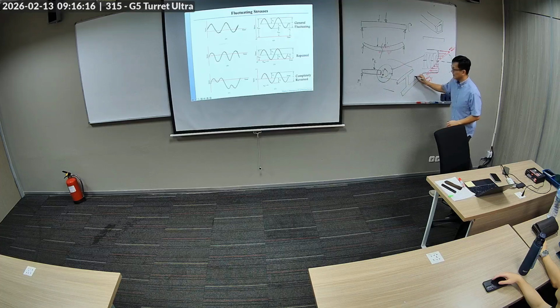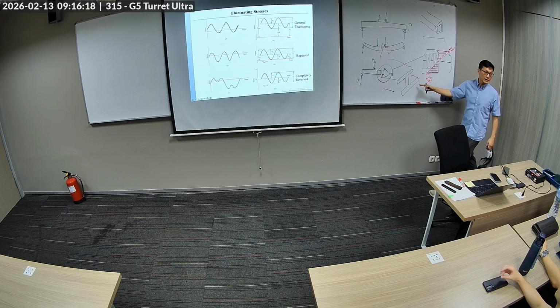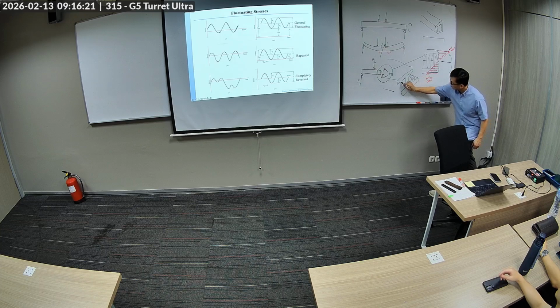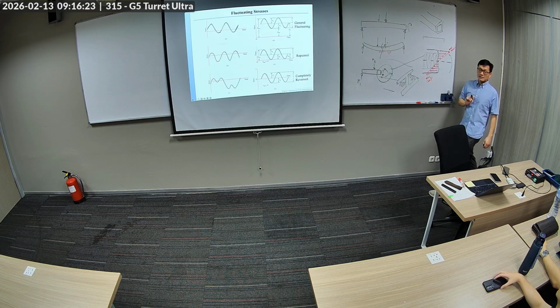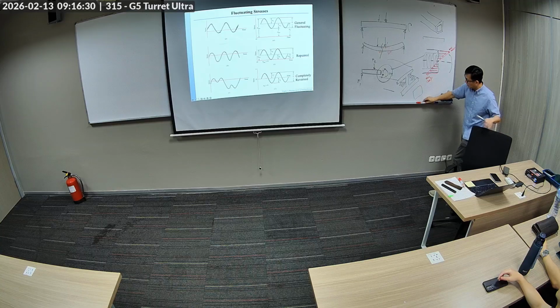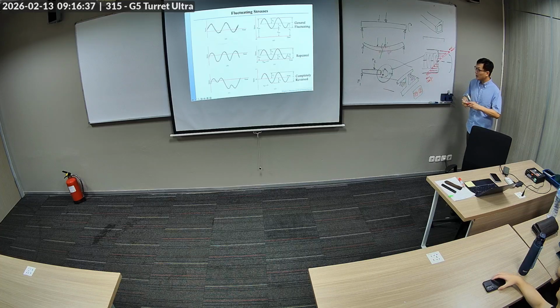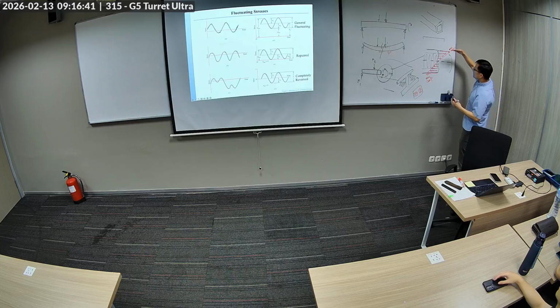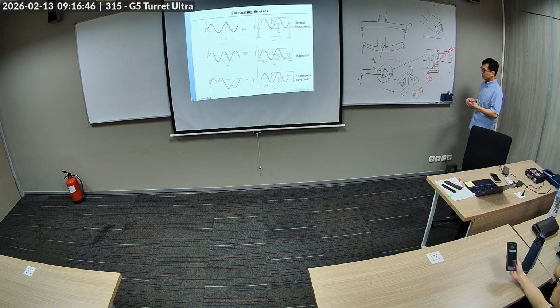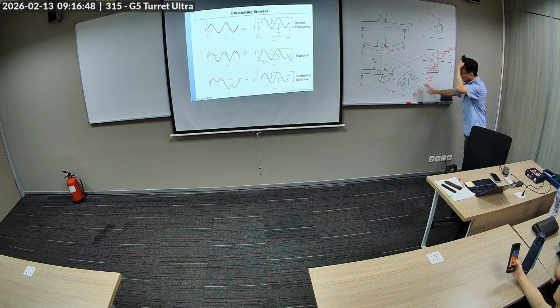You have beams like this, with a cross-section like this. Why? Because the middle is not doing much. So I get rid of the mass. Why would I make it a solid block? Because the middle is not doing much, I cut it out. And so what I end up with is an I-beam. And that's why you see this in construction, because with bending, what is important is the top and the bottom. Okay? So, going back to shaft.